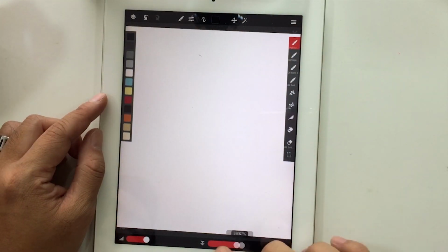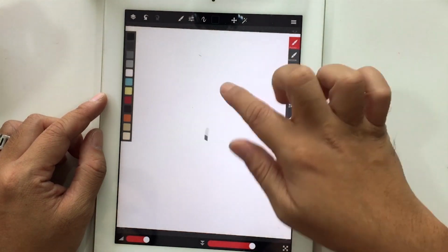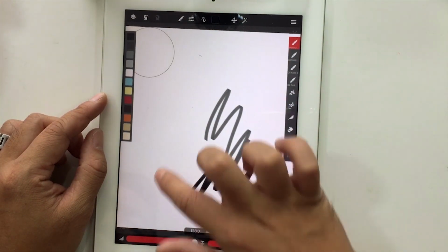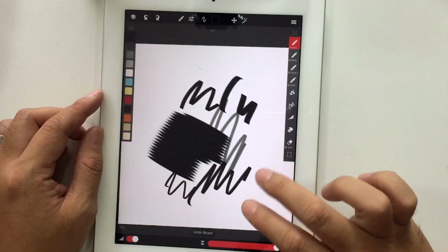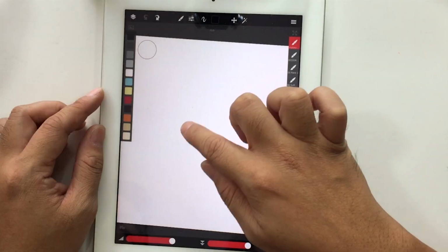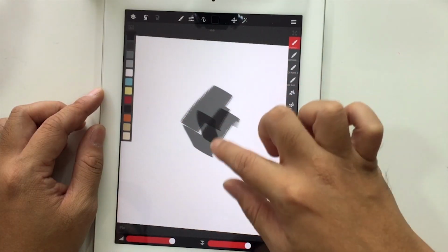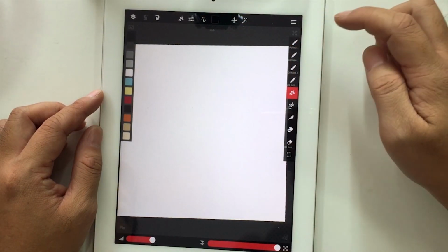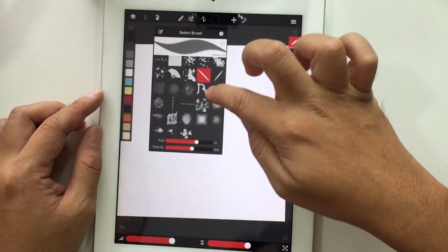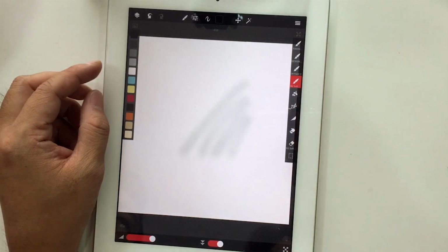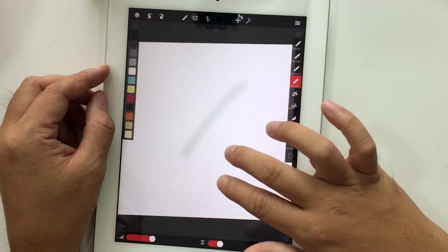So here is the opacity of all your brushes. Let's say I just paint something. This is the size. Everything you have in Photoshop, you have it here. Go to the preferences to set undo to be just a double click, and just block out some shapes that I like. Go to brush, change your brush to different textures, or use a soft brush to create gradation or transition.